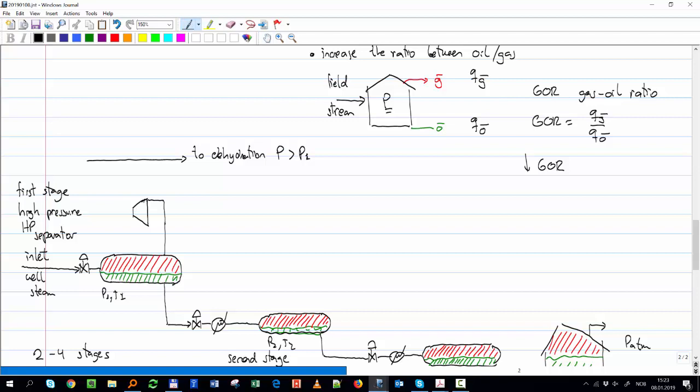So how do we solve this problem? First, the way it is solved, I don't put the compressor right away, but I put a cooler, such that I try to make it even cooler, and even more liquid will drop out.